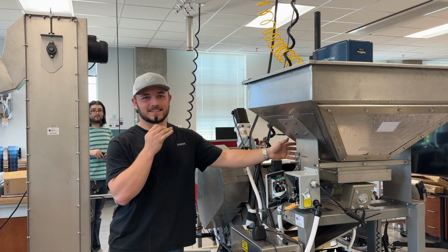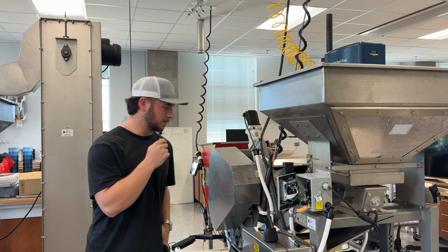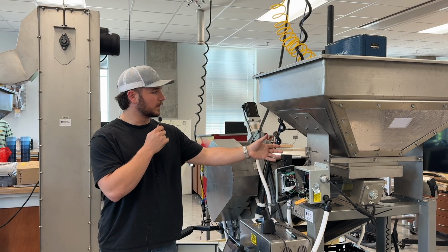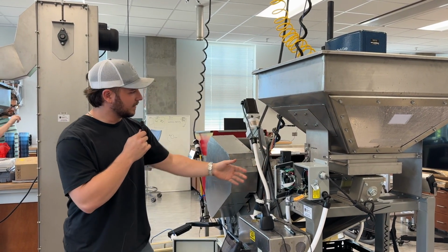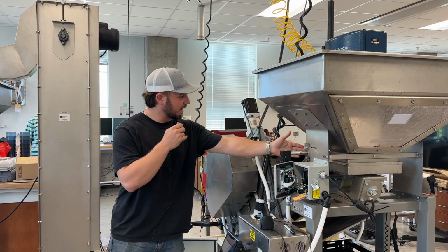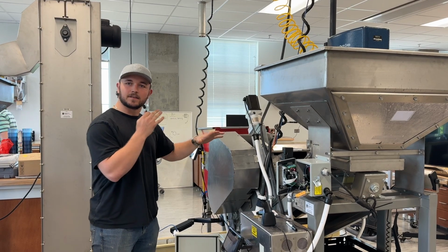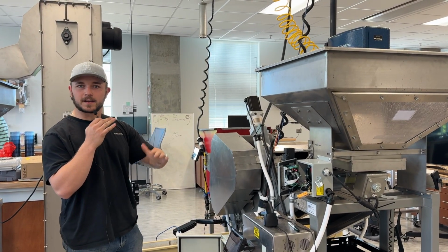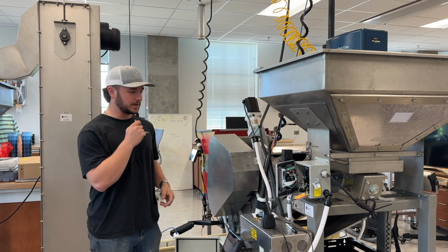Here we have our JC cracker. This is our more high throughput cracker. We're able to do more pecans in a short period of time. The way this cracker works is you have a hopper here and a vibratory conveyor, and this conveyor shakes and moves the pecans along and dumps them into this machine, which has a large plate that is on cams, and it's impacting the pecans over and over again at a certain frequency, which we can change.